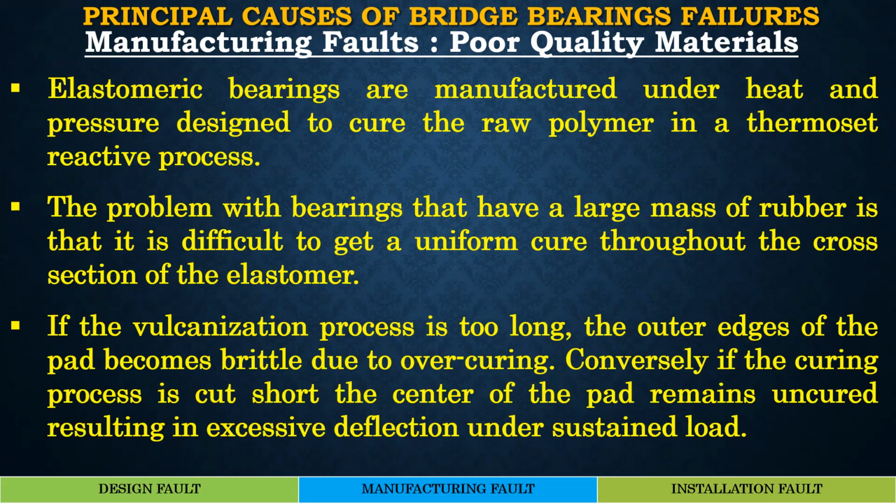Now, you see, the elastomeric bearing is one such material which, if done properly, is in fact one of the best bearing types, which has very good resistance against earthquake, and therefore I would strongly recommend use of elastomeric bearing to the maximum extent possible, as long as you are able to satisfy all the requirements of elastomeric bearing.